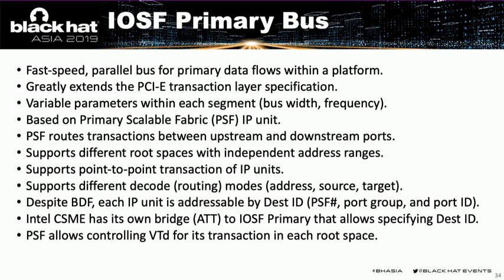Also, the IOSF primary bus supports different decode or routing modes. For example, the PSF unit can select a target port or target device for a transaction based on its addresses, or a source of a transaction can explicitly specify a target device by a special identifier named destination ID.